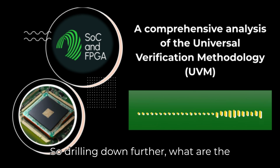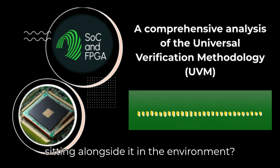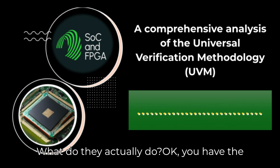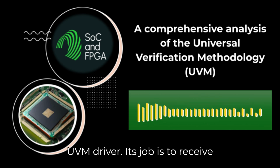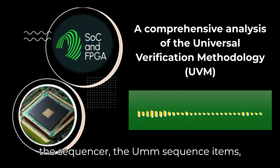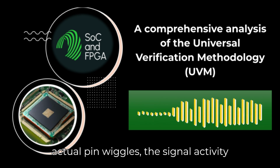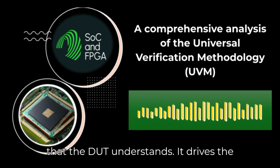Makes sense. So drilling down further, what are the core pieces inside an agent or maybe sitting alongside it in the environment? What do they actually do? Okay, you have the UVM driver. Its job is to receive those abstract transaction objects from the sequencer. The sequence items. Right, and it translates them into the actual pin wiggles, the signal activity that the DUT understands. It drives the physical interface.